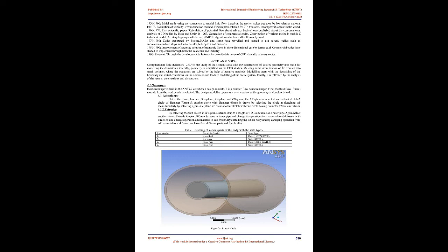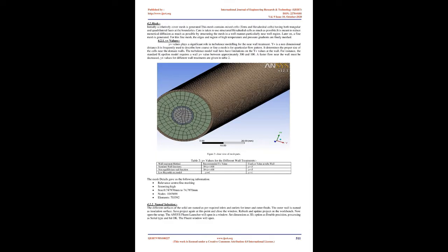Mir et al. studied numerical simulation of the steady, laminar, forced convection heat transfer in the finned annulus for the case of the fully developed incompressible region of a finned double pipe subjected to constant heat flux boundary conditions. They found a significant enhancement in heat transfer rate and also Nusselt number. For small numbers of fins, fin geometries like fin height, ratio of radii, and half fin angle were found to be less influential.